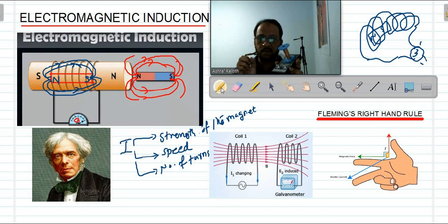It is not like normal bulb. If you give battery positive to positive of the LED and negative to negative of the LED, then only it can glow. If you give reverse connection to the LED, it won't work. It will not glow. It will not give light. Got it? So here these two LEDs, positive of one LED and negative of other LED are interconnected, and vice versa. And that two common points are connected to two ends of this wire.